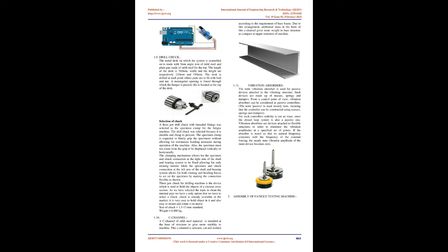The bearing housing is a cylindrical hollow-shaped steel material possessing good strength and toughness. The housing design was implemented by selecting dimensions that will result in a smaller minimum bending moment, which is desirable, or realistic shaft geometry in order to produce the required bending moment. The housing was bored to the size of the external diameter of the chuck, which is 25 mm. Two bearings were then forcefully inserted into the housing at both ends.